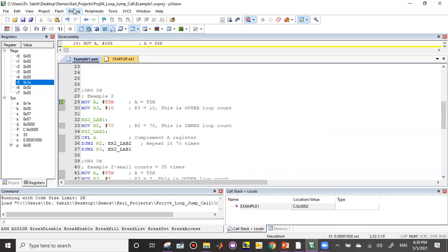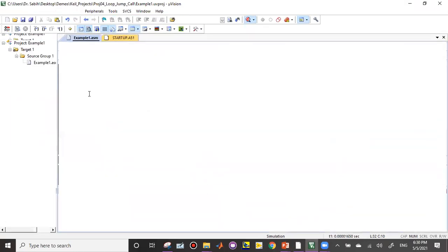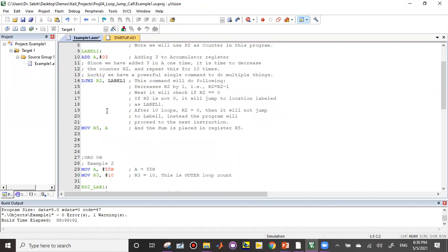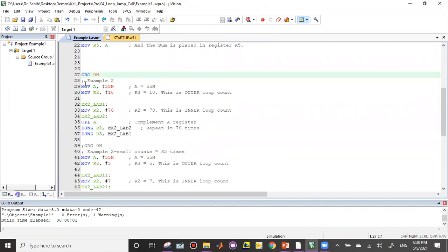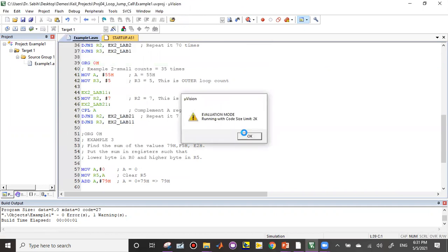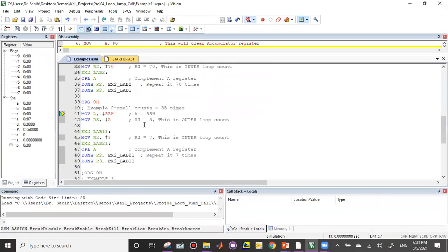Now, let me stop it. Right. And I will make a small trick here. So I comment this one, and remove this 2, and even not here, this one, the small one. So now when I compile the code, all these instructions will be forced to be at this location. So the program counter will come directly here.